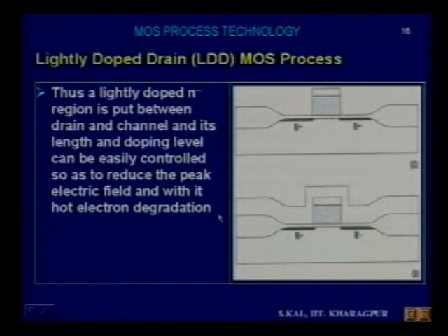That is our aim. So we have to adjust the length, width and doping level of the reach through diffusion or implantation, so as to reduce the peak electric field and with it hot electron degradation.